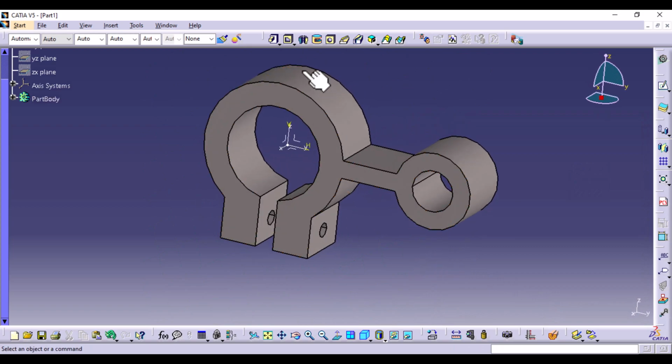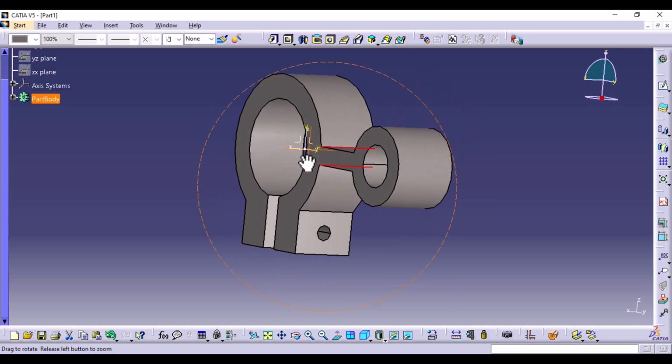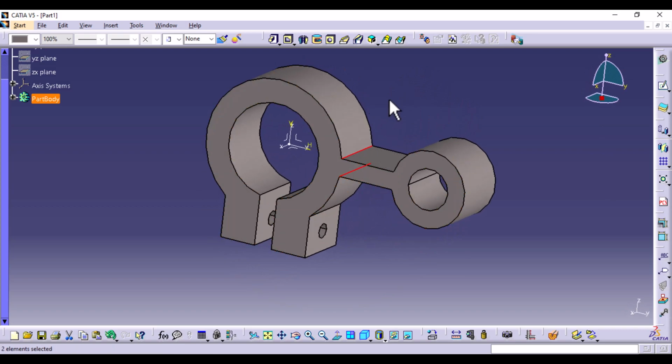Lastly, we want to create the stiffener here, but before I do that, I'm going to insert the edge fillet first. You can do it after. I just prefer to do it before. Unless you are creating more surfaces, you don't want to do the fillet before when you're creating surfaces. But here, because this is the last structure we're going to create, I can do it.